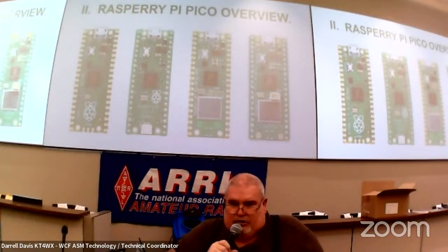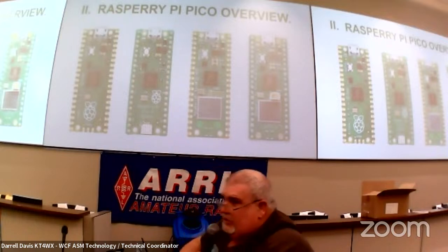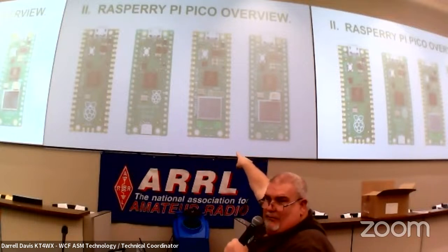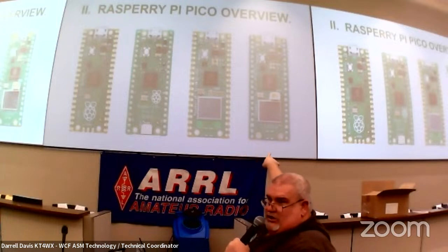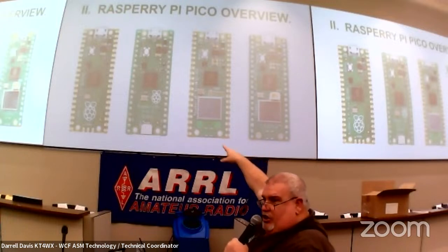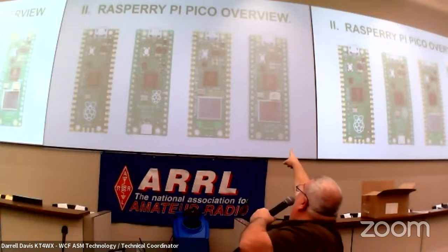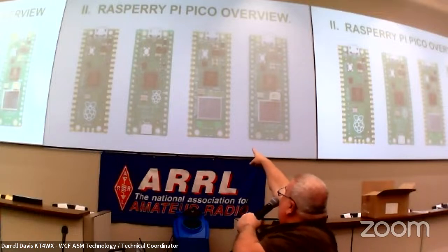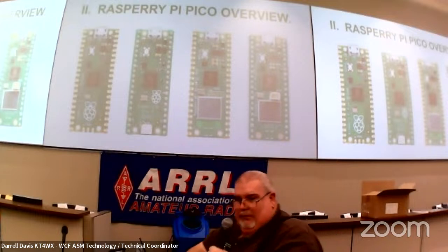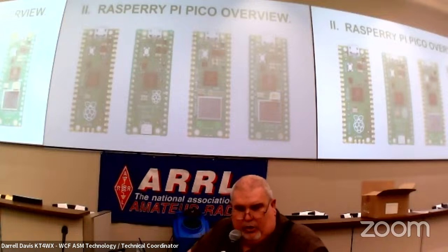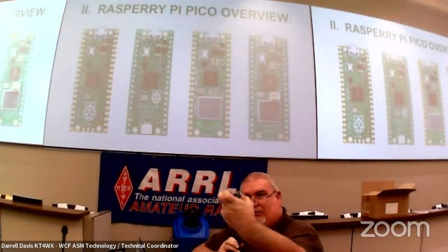And you see the next 2, notice they got that little shield right there you could see on the chip. That's the wireless transceiver. That's an 802.11 transceiver IC. It's got a shield over it. And one is without the debug connector, and one has it. You can see it's not soldered onto that one. It's soldered onto that one. And I bought the one, I think, without the serial wire debug, but mine's got the wireless option.